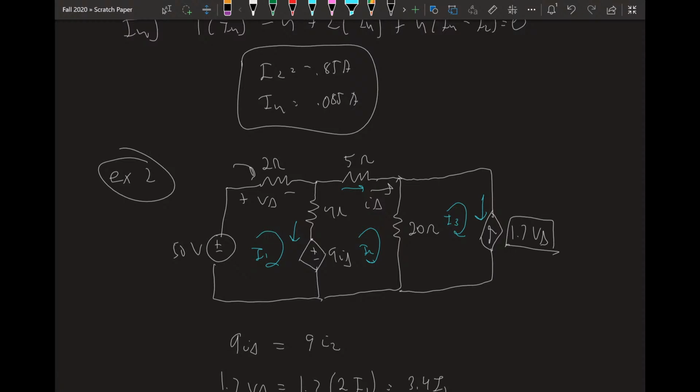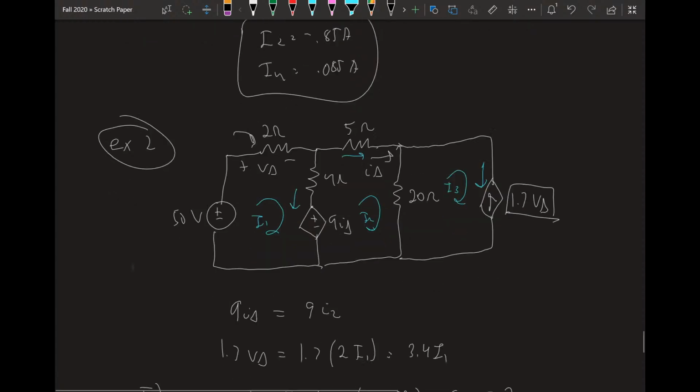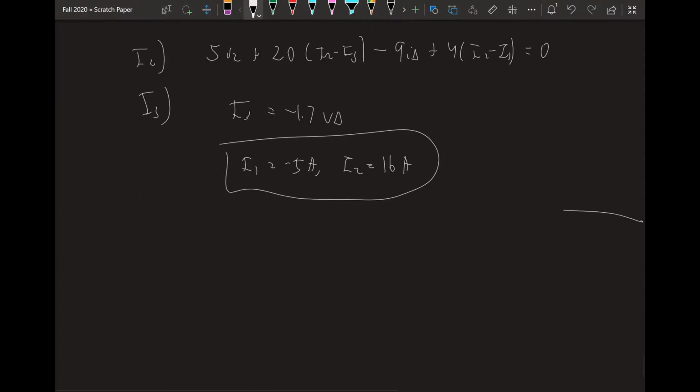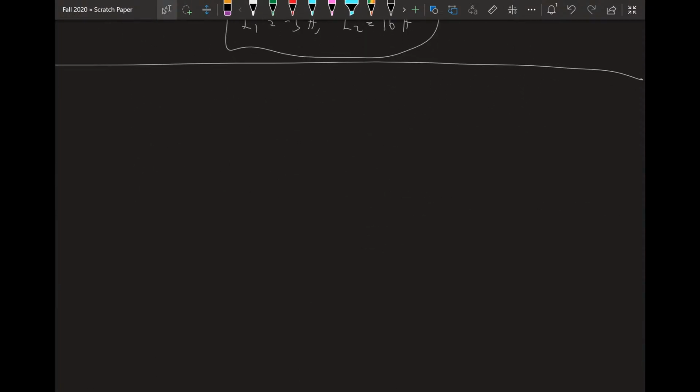Okay, so I can do superposition. So that was the end of the stuff I know it's going to cover. I'll do op-amps since you guys covered this week, and you guys seem to not have heard of Thevenin, source transformations, etc. So we can just start with some simple op-amp problems and then go from there. So, op-amps. Well, first of all, what is an op-amp? An operational amplifier is a device that amplifies the difference between its positive and negative terminals up to its voltage rails.